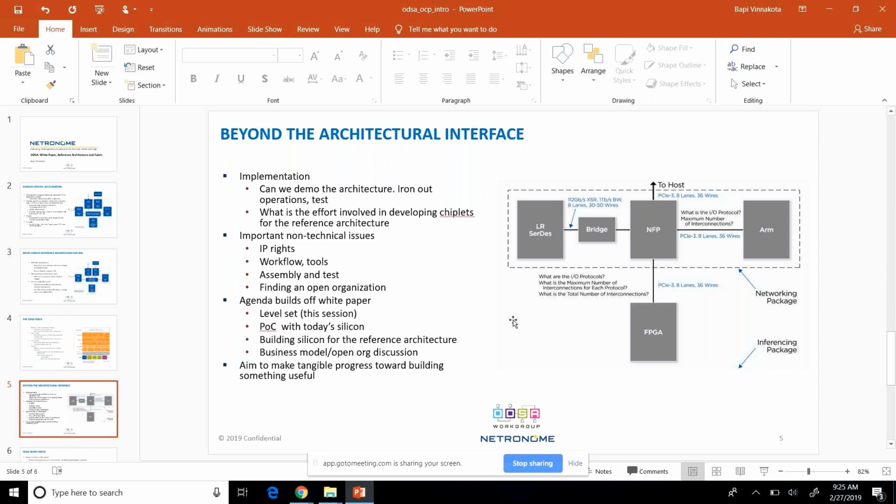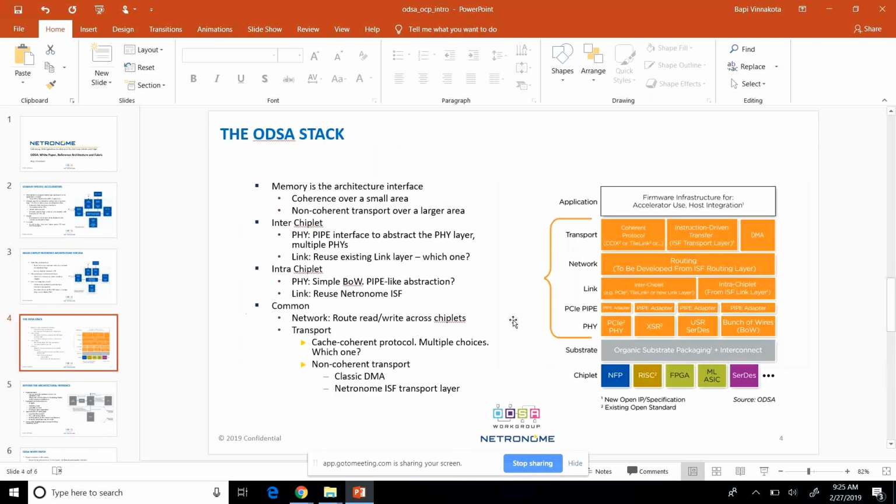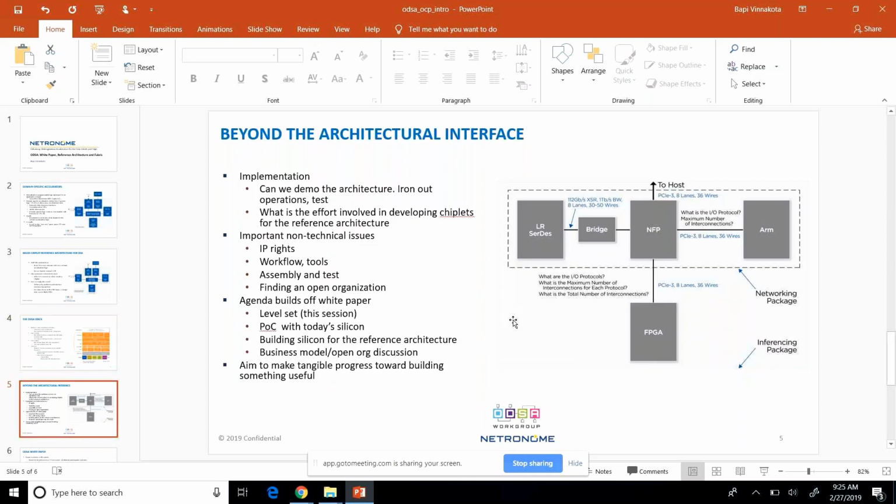The third is an FPGA die, and the fourth component is a long-range PHY. So the idea is that we take these four die from different companies, integrate them into one package with some prototype version of the open architecture interface we're developing. And in fact, slotting that package onto the open accelerator card might actually be a pretty interesting thing to consider.